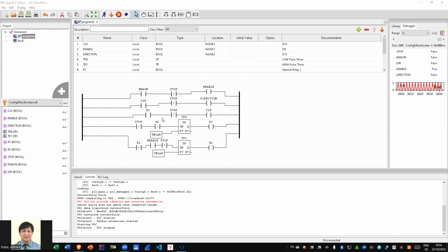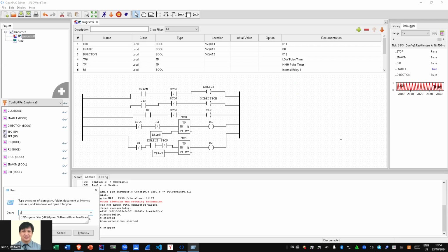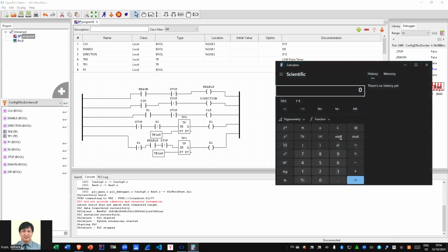Okay, so the next question is, how do you control the rotation of the stepper motor? We all know from the previous video that we can operate the stepper motor driver and drive the motor. The question is, how can you set the number of rotations for a specific stepper motor? The answer lies with the ability of the motor. Motors themselves have a minimum step rating. How many degrees per each step?